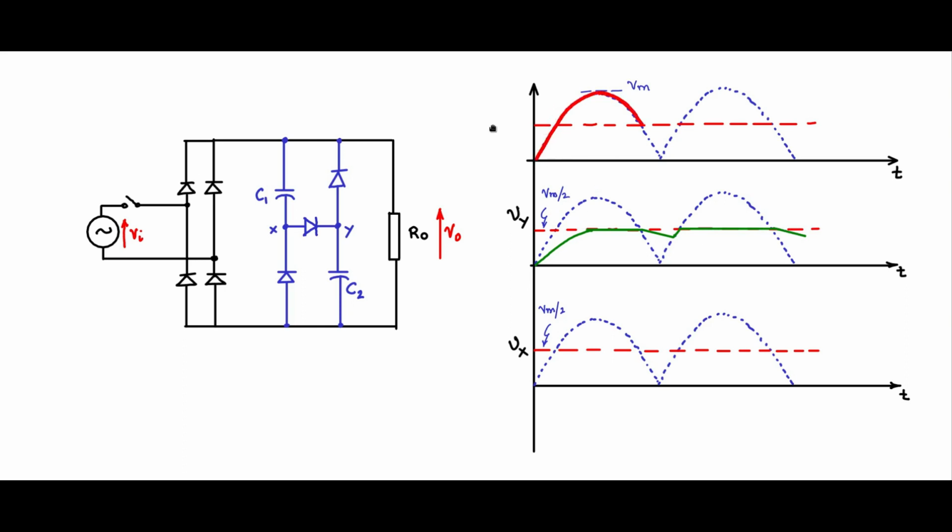Now if you look at the envelope of the output voltage, in the first cycle it goes in this fashion up to the point it crosses over and comes to the Vm by 2 point. It is tracking the input. Now at this point these diodes switch off and the output is just the capacitor voltage, which are discharging like this. And then at this point again it will start tracking the input and comes down, and then again here you will see it will track the capacitor voltages. So now this will be the output voltage envelope. Look at the very large ripple, but look at the conduction time. The conduction time is all this time, the current conduction time.